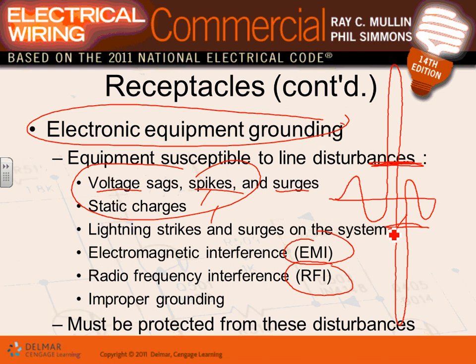So long story short, guys, all of these, from an isolating ground receptacle to an insulated grounding conductor to surge protective devices, will maximize the survivability of your electronic equipment. And if you are the manager of a building and every time you have lightning you burn a couple of receptacles, a couple of laptops, you fully understand why they have this system. Any comments, guys? Any questions?